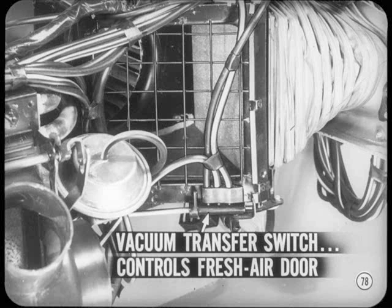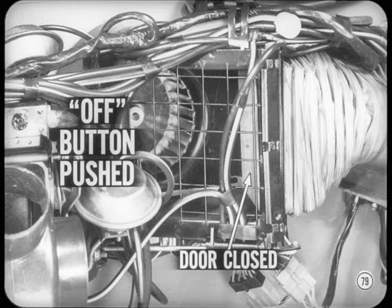Another component that you won't find on conventional air conditioners is a vacuum transfer switch. This switch combines with a spring and a vacuum actuator to control the position of the fresh air door. With the engine running and the off button pushed, the fresh air door should be closed. You can check this by reaching through the grill and pushing on the door.